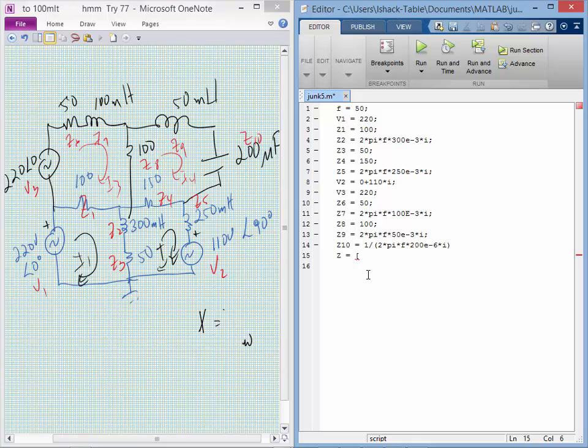It's going to be Z1 plus Z2 plus Z3. The next one is going to be minus Z2 plus Z3. That's the same. Now loop 3, now I've got minus Z1 there, right? Loop 3 and loop 1 has this shared component, minus Z1, and 0 for the next one, because between loop 1 and loop 4, there's nothing there.